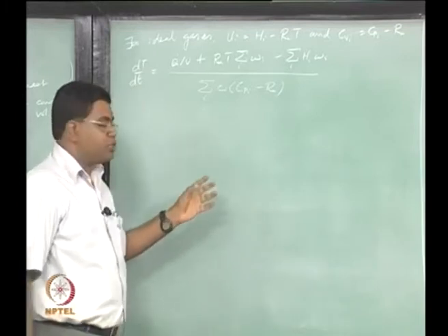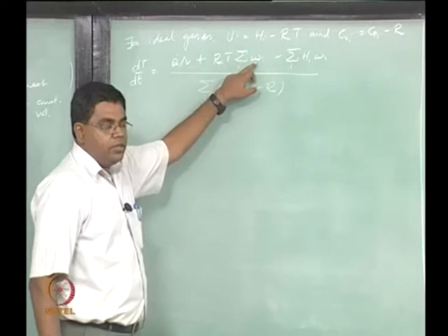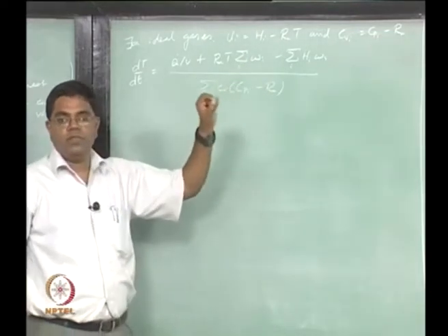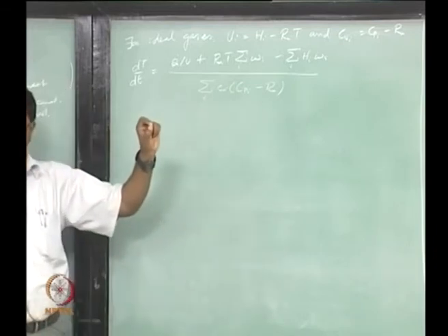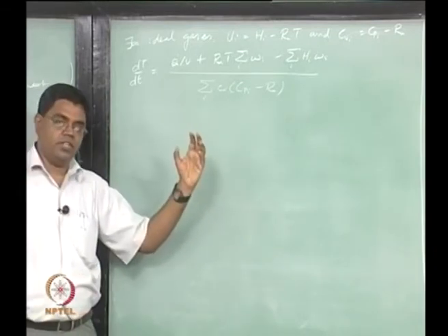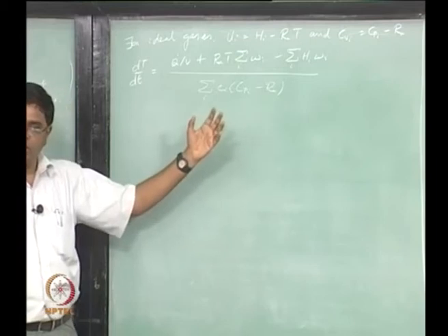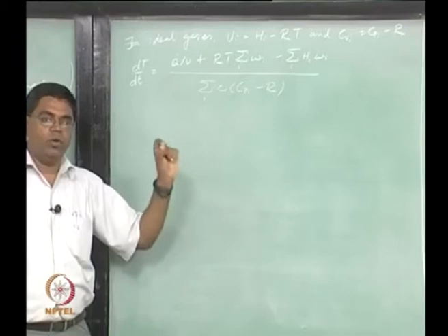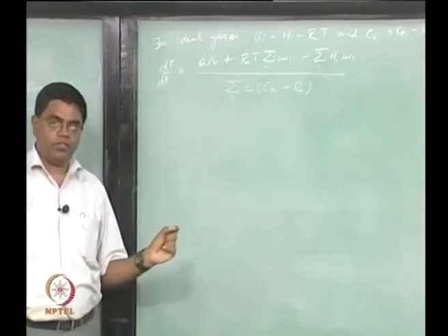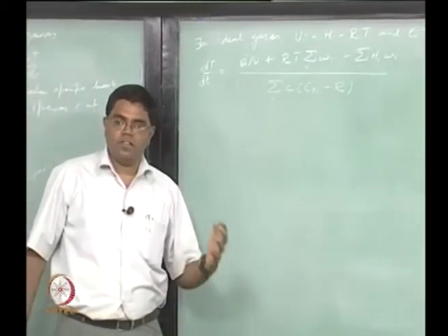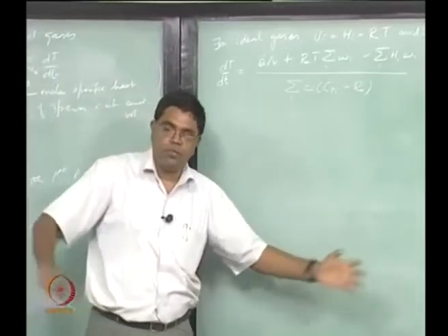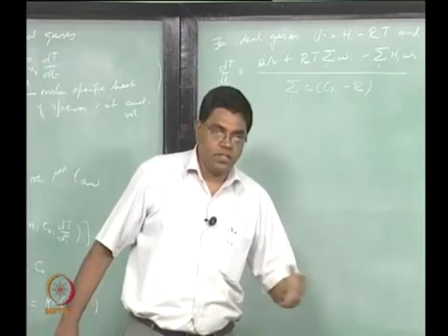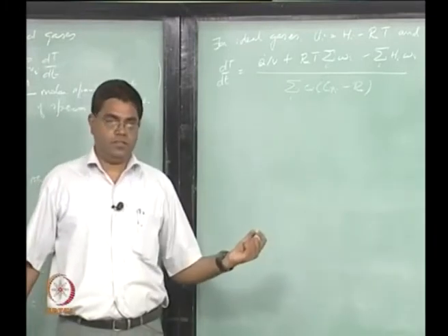So if we were to look at small omega_i as the amount of mass that is produced per unit volume per unit time, for which we will assign a symbol W_i later on, then sigma over all i of W_i will be equal to 0, because you do not have any net mass that is produced or consumed if you sum over all the chemical species that are produced and consumed on their mass basis.